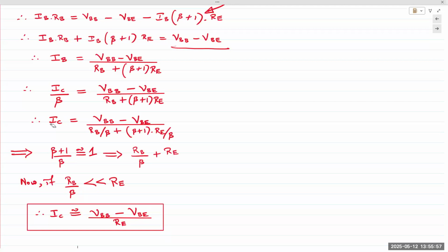One final point about this would be that if this beta varies 35 to 100, we have to account for that value too. It could vary from 35 to 200, let's say, right? So within one single transistor line, beta could vary widely from 35 to 200, maybe from 50 to 300. So if that happens, we have to consider those values when we are choosing the values for RE and RB.